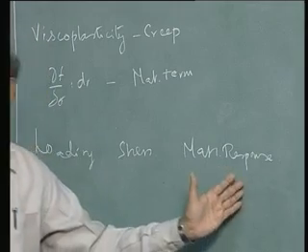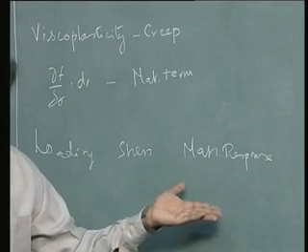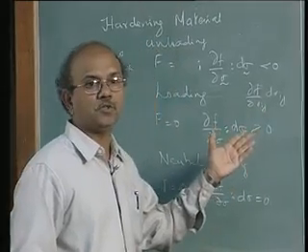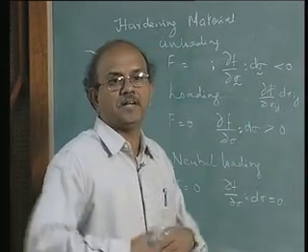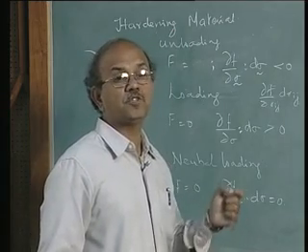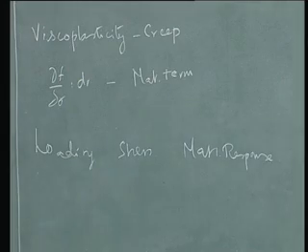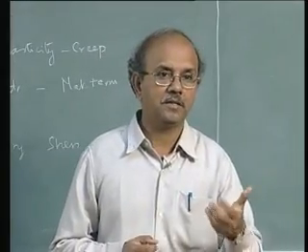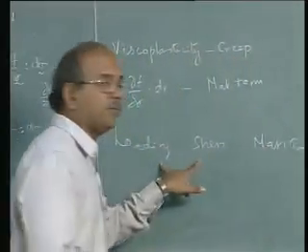That is the third thing that we are looking at. It is the material response which decides whether we are looking at a rate independent solution or a rate dependent solution. Because the material responds in a particular way at a higher temperature, we are looking at the material to behave in a viscoplastic fashion. So plasticity and viscoplasticity are mathematical models for the phenomenological issues that take place. Is that clear? So this is the equilibrium equation.